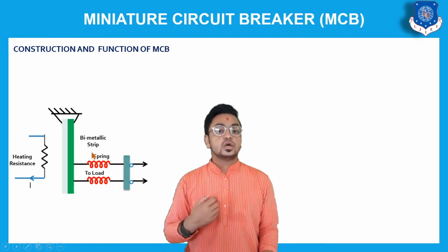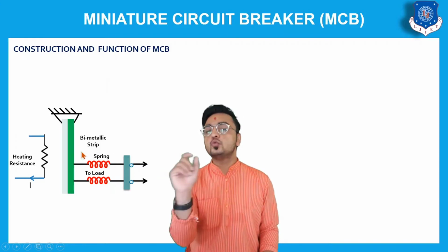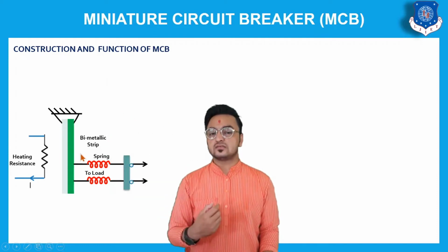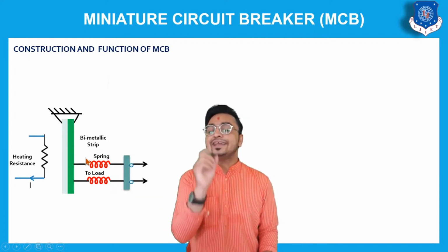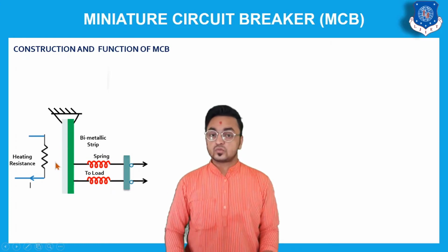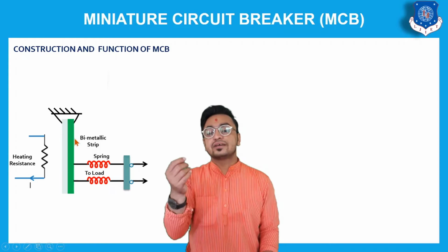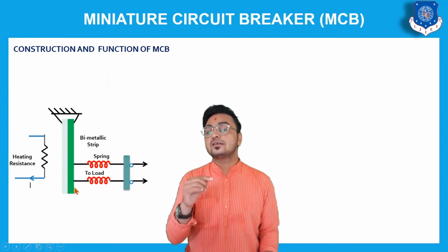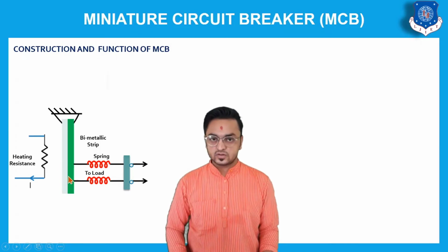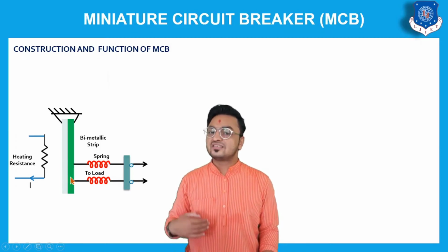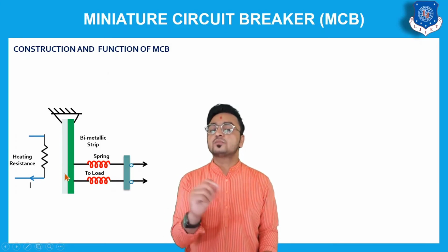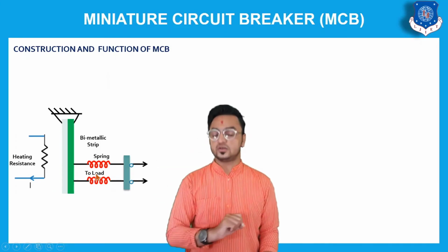Basically if we increase the temperature of these two plates, the length of both plates will increase, but that increment will be different for the two plates. The length of this green color plate will increase more compared to this light color plate. So when we provide the same temperature difference, the change in length of these two plates is going to be different.